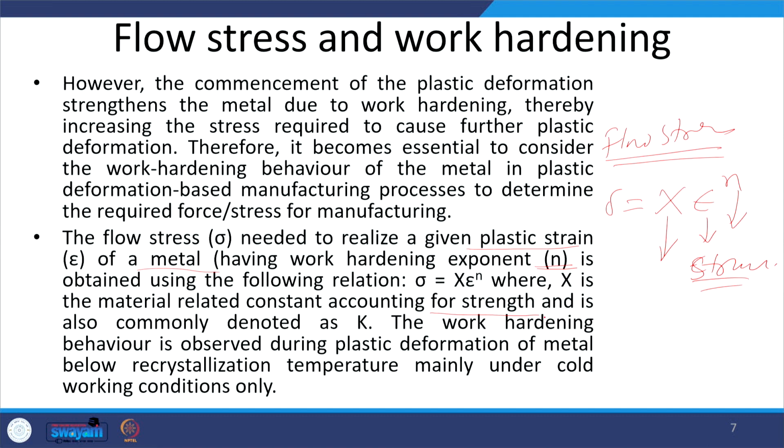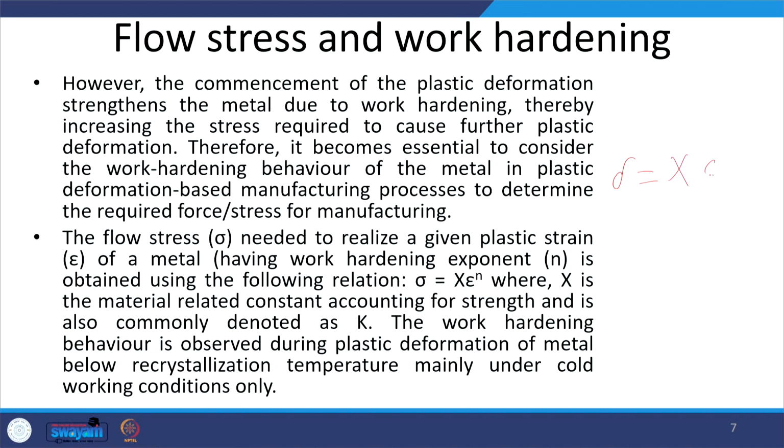Okay. Then the work hardening behavior of the material is observed during the plastic deformation of the metal below the recrystallization temperature. So, the increasing stress requirement with the plastic deformation is true especially when the deformation is done under room temperature conditions. If the deformation is carried out at a high temperature, then the material does not show the work hardening behavior. So, the flow stress to cause the given amount of plastic deformation can be obtained by this equation.